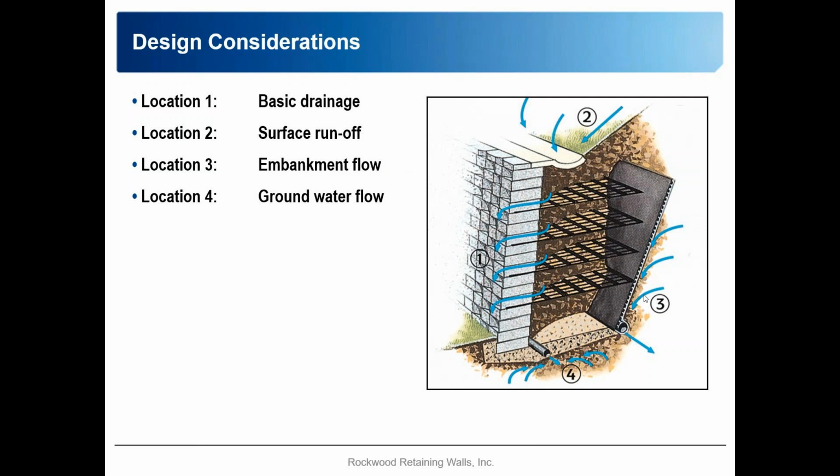Third line of defense here is typically more site specific. As I explained a couple slides ago, we either have a fill wall or a cut wall. It's not very common that you would see this drainage composite, or what we call strip drain, in a fill wall application. However, in some cut wall applications, there may be water that could seep from the embankment, an old hydrostatic head, that when the excavation occurred, now we're starting to see water seeping out of that embankment.